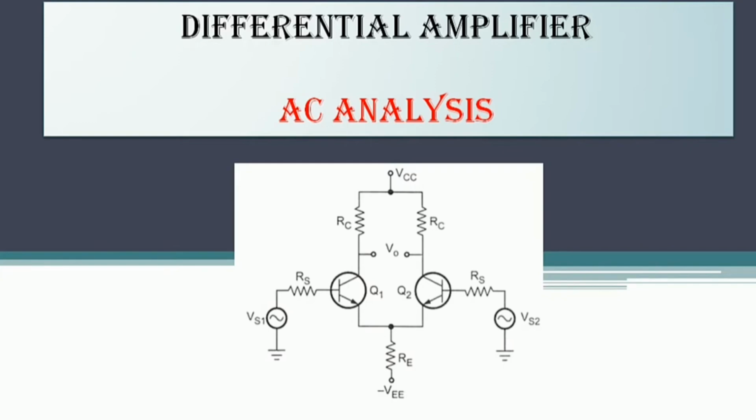What do we mean by small signal? This AC analysis allows you to figure out what happens to your circuit when you apply millivolt signals without any noise. If you apply millivolt signals without any noise to the circuit, how will the output response be? What is the gain of the circuit? This is calculated by considering small signal responses of the circuit, with the help of the H parameter, R parameter or the T model.